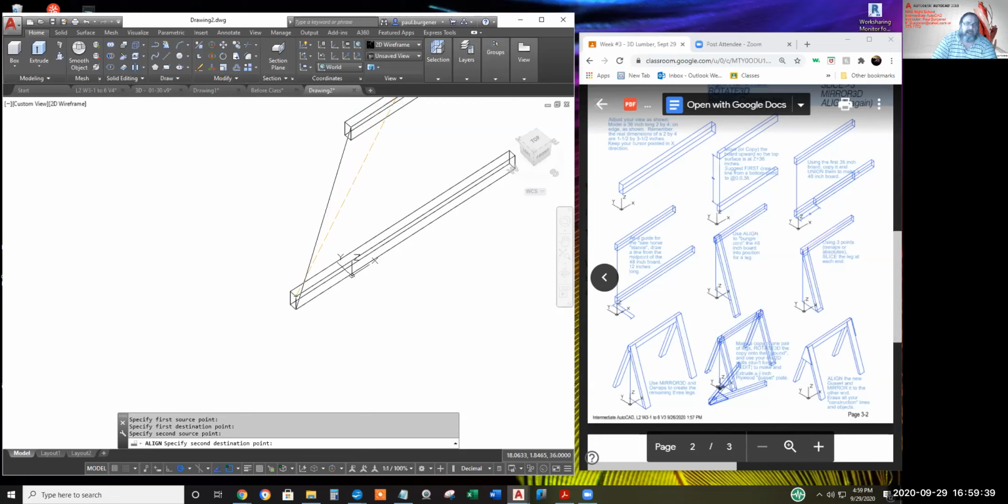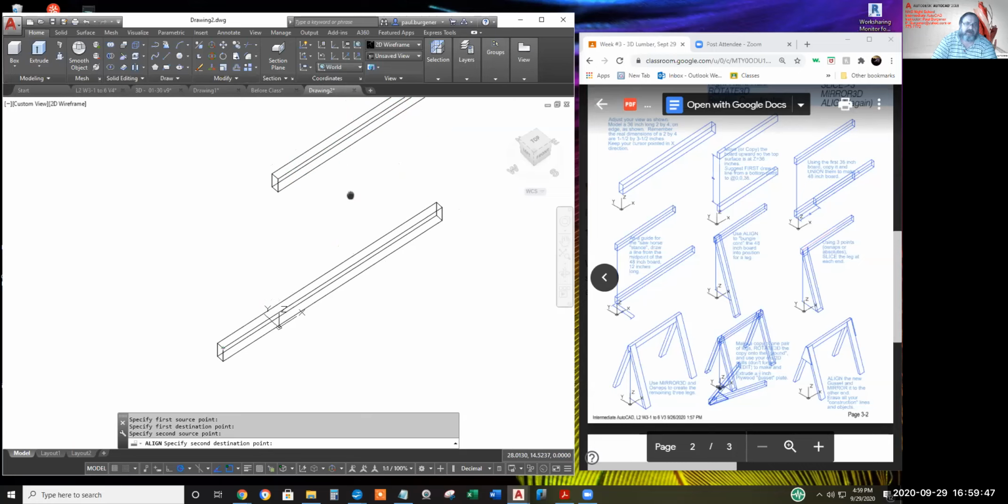Now, as soon as I pan so I can see the triangle at the midpoint, I expect this black bungee cord will disappear. Let's see. Yep, there it goes. But I'll slide up from the end point and O-snap on the midpoint. Notice there's midpoints of different edges close together, so double check you're on the proper midpoint.